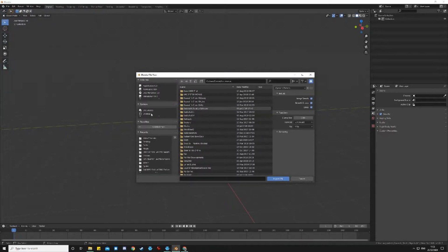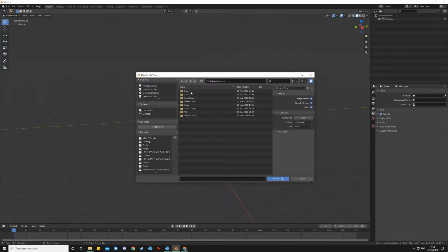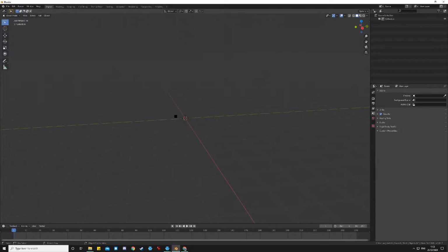So within Blender, if we just go to mouse, I just got to find it, there you are, mouse folder, Meshroom Cache, texturing in the folder with the long name, and all I need to do is click on this one, which is the obj. It'll drag in the textures, it will drag in the MTL and all that stuff that we will need at some point, but you just need to do it from here initially. So we import the OBJ. That square means it's loading, and it's just spending some time working out where it all is.